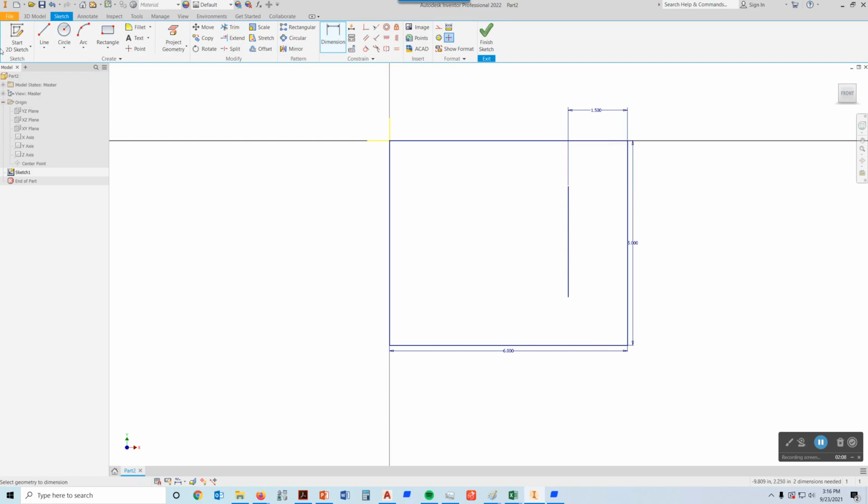All right. Now I want to have a line from somewhere along here to the end point of that guy, like that right there. And I need to put a couple of dimensions on there. So I want a dimension right here. Let's see. Actually, I got to be careful. When I put that dimension, I want to go from this corner to this corner here. And I want to make that 0.75 and press enter.